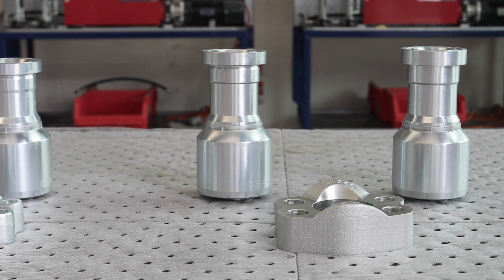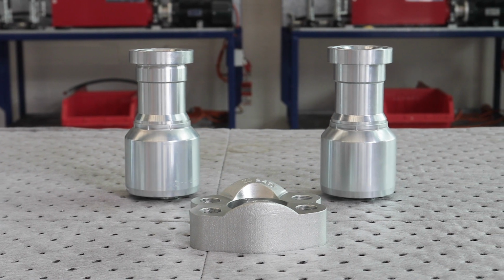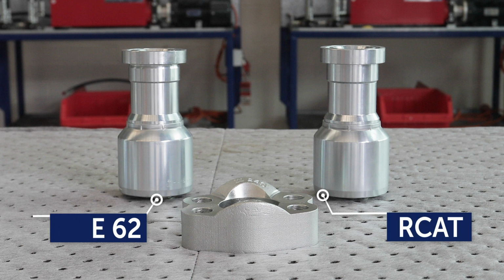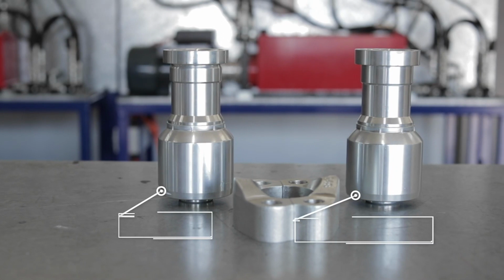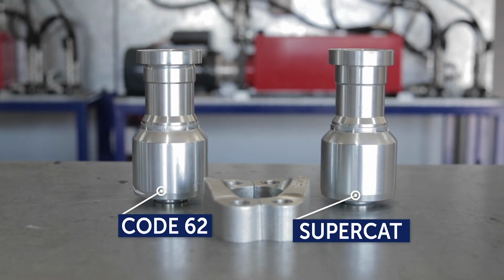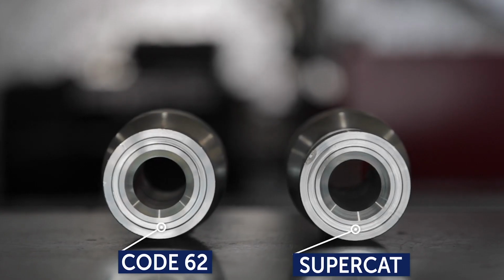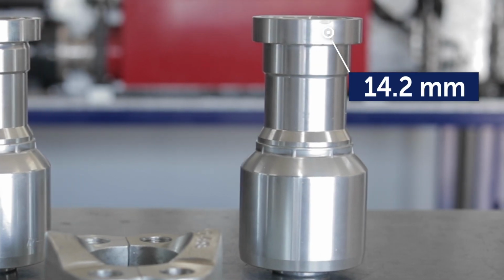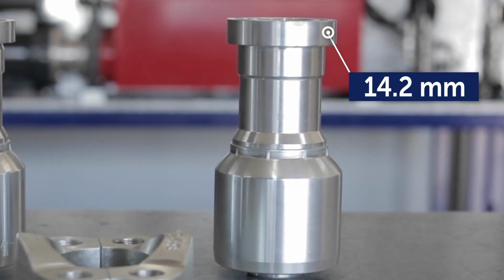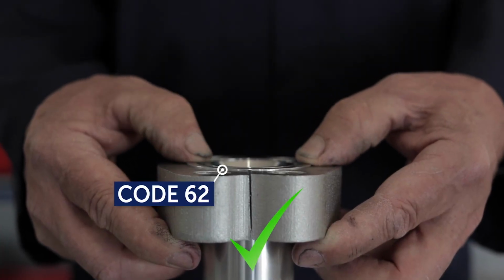Moving on to the last of our selection, both these hose tails are rated at 6,000 psi. These hose tails are known in the industry as Code 62 and Supercat. The flanges appear to be very similar. In fact, the flange diameter and O-ring groove are exactly the same. Generally, all Supercat flanges have a thickness of 14.2 millimeters, whereas the Code 62 flange in this instance is thinner by approximately 1.5 millimeters.